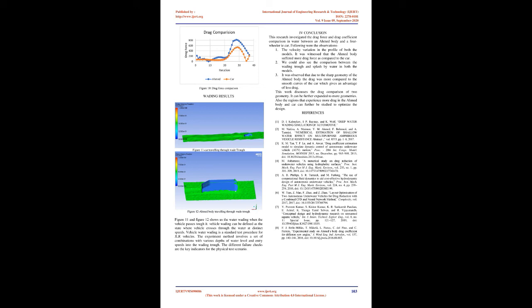3. Results and discussion. The results obtained after simulating both geometries are analyzed. The different contours of the flow are shown in Figure 8 and Figure 9. It was seen from the contour and the streamline of both car and Ahmed body that the velocity is low in the front in the car due to more drag, and in the case of the Ahmed body the velocity was not reduced. Figure 9. Contours and streamline of the Ahmed body.